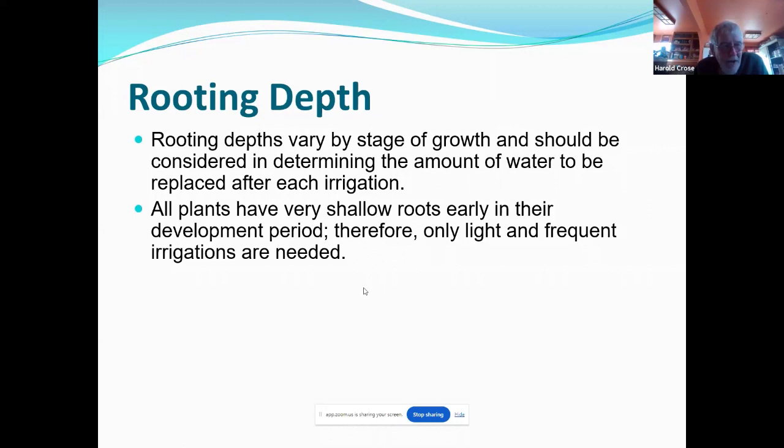And getting back to center pivots, and this is a good example, when they run those pivots on a complete pivot and stop it in the same place every time, half of your irrigation is happening at night and half of it's happening during the day. The consumptive use during the day and evaporation is a lot higher than it is during night. So if you're stopping the same place every time and you're irrigating half your field at night and half during the day, half of your field's going to be underwatered and half of it's going to be overwatered.